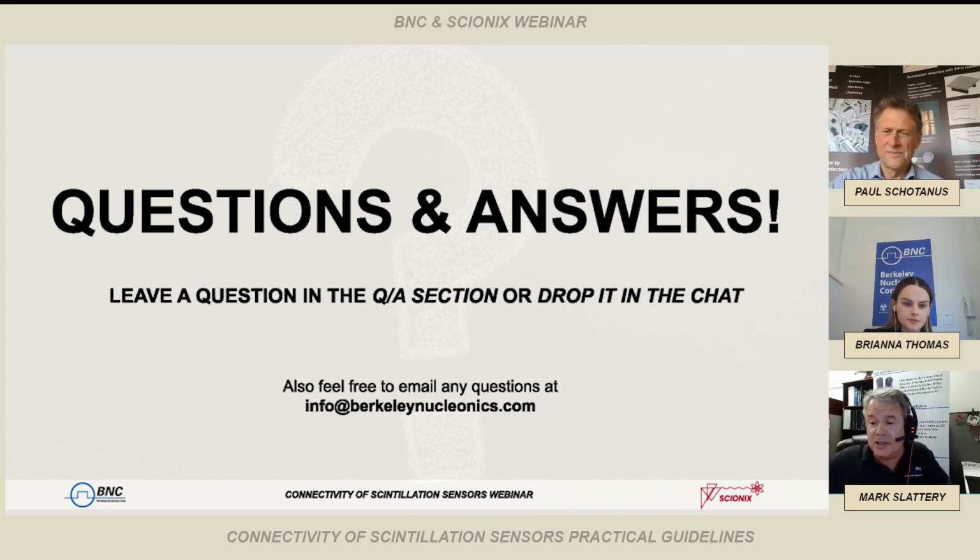Wen Zhao, last question. He says, is it better to choose a higher impedance or low impedance scope for the measurement of a SiPM's output? Well, if you're just examining your signals, it doesn't really matter if you terminate the signal with 1 megohm or with 50 ohm. If you're using 1 megohm, of course, you see more amplitude. Your signal amplitude is much higher. With 50 ohm or even lower termination of your SiPM signal, you see the real speed of your sensor, the maximum you can get out of it.